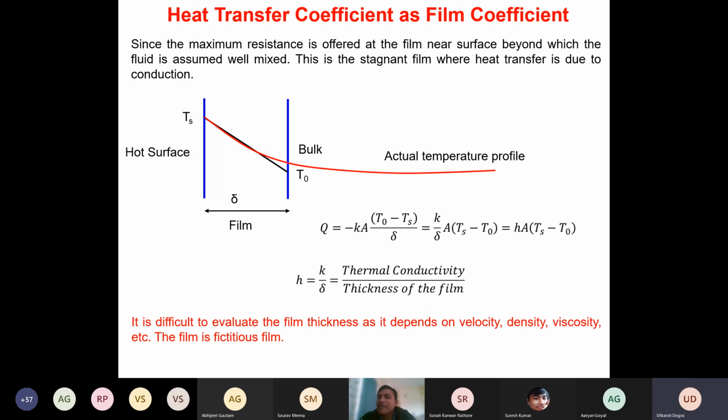convection, sorry. In natural convection, we will see the derivation of one simple problem where we are looking at the laminar flow. So only for laminar flow we can derive. Remember the Navier-Stokes equation we can simplify for a laminar flow, isn't it? Right. So for only a simple case of pipe flow with a laminar flow condition, we will derive the entire heat transfer equation again when we look at natural convection. Okay, but for the time being, let's do our analysis based on only this heat transfer coefficient. Is it clear to everyone?